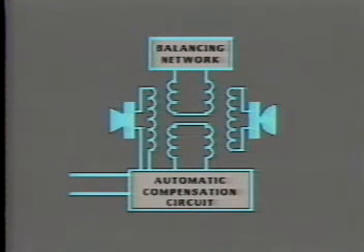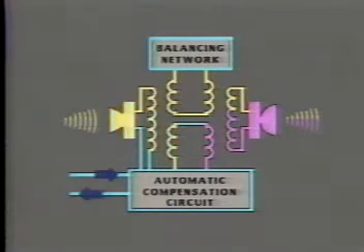In our telephone set, there is a balancing network which permits a small amount of transmitted signal to be fed to the receiver. This is called side tone. Side tone is the hearing of one's own voice in the receiver while talking into the transmitter. Tests have confirmed that too much side tone encourages callers to lower their voice, while too little side tone causes them to talk too loudly. The purpose of side tone, therefore, is to satisfy the caller that the telephone is indeed working and to control talker volume within predictable limits.